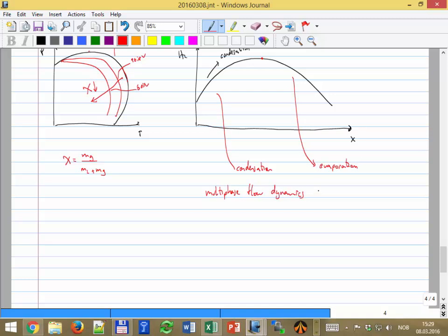That means the velocity of the liquid begins to go down compared to the velocity of the gas. That means the gas is flowing quicker. Then as the gas is flowing quicker, it requires less cross section. So the liquid layer begins to go up. That could also be an option.